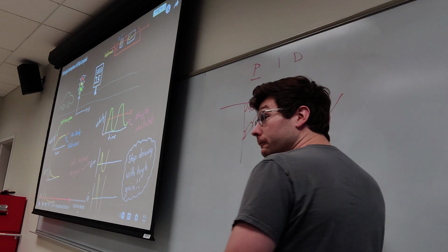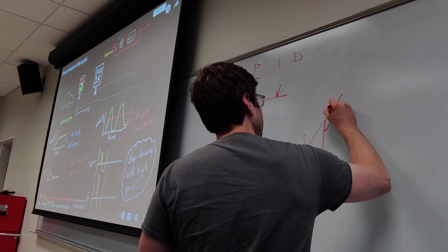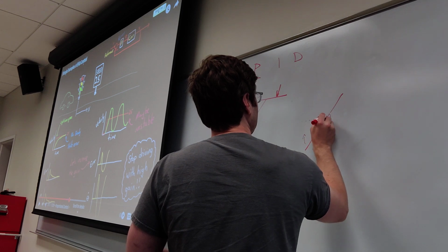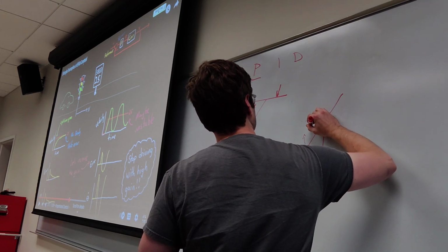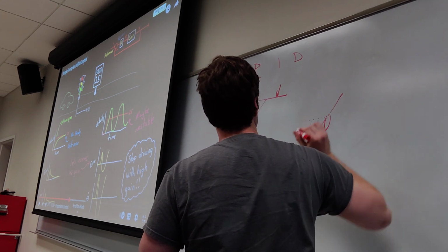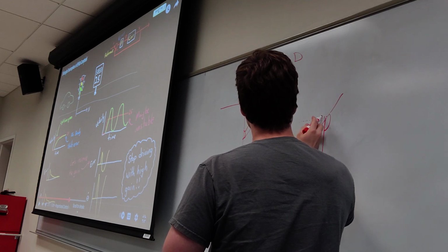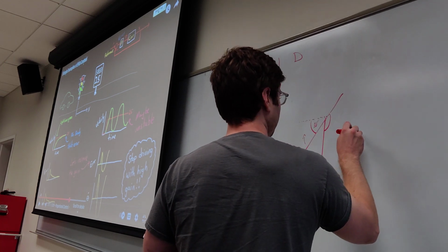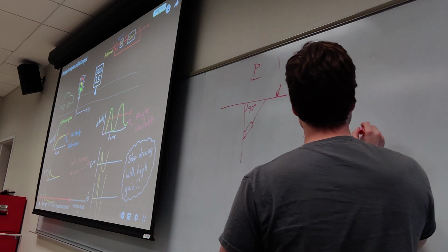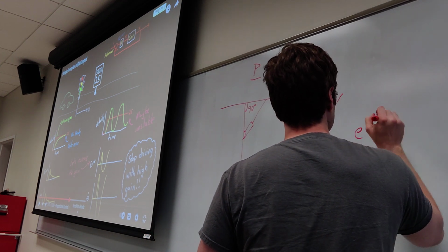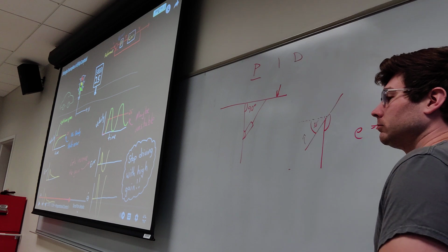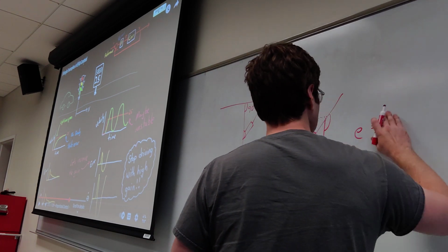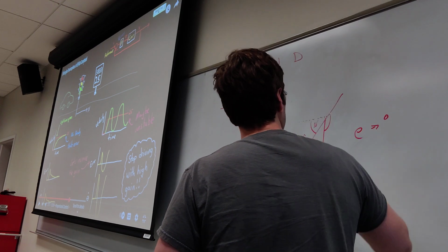The force with which that motor moves is proportional to the difference. See this angle right here? This is our set point, and this is where we currently are. That's our error, E. Here it's an angle, degrees, might be radians, might be a speed value, whatever units we're working in. So this is our error.